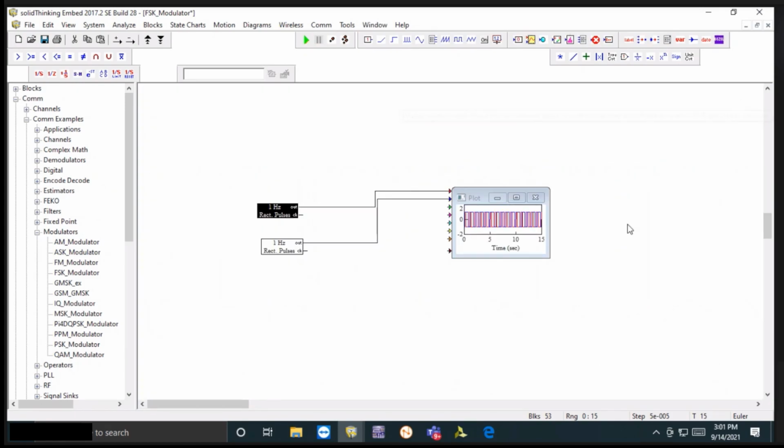Now about the QPSK, you know what we have to do. We have the master signal, a stream of bits. So from that, on the basis of the position of appearance, we divide it into two categories of odd and even bits. It's not like we have the 1 bit or 0 bit or 1 or -1. No, we have a train of symbols, random symbols, because we have the master signal.